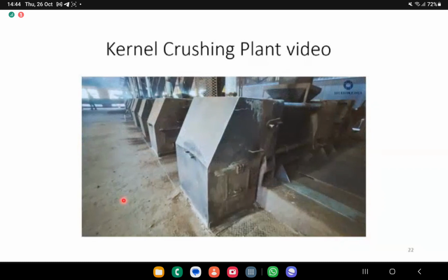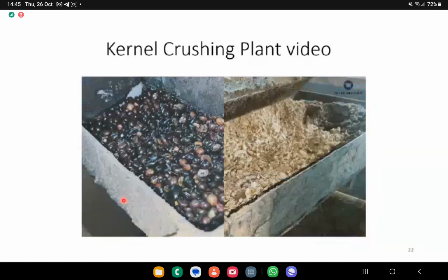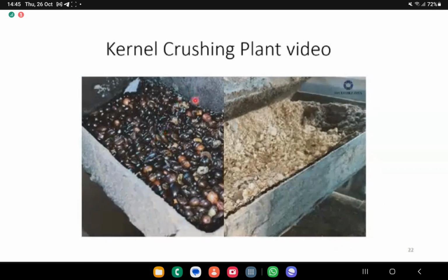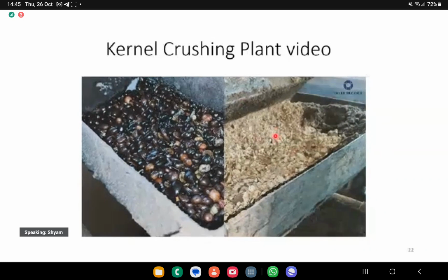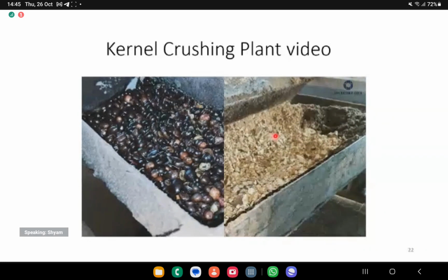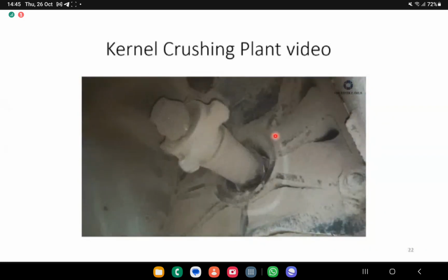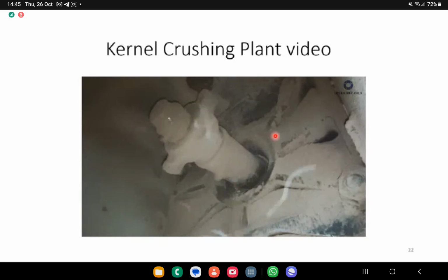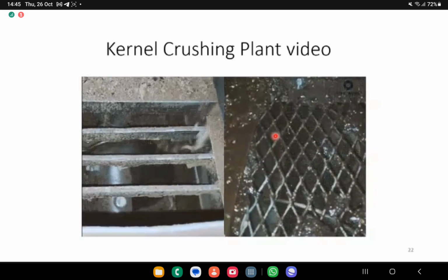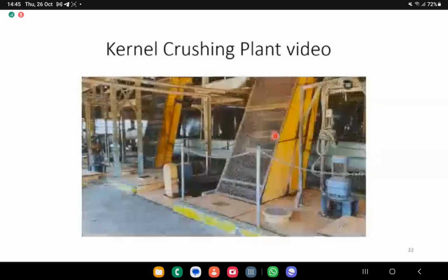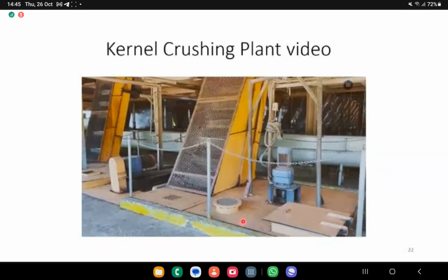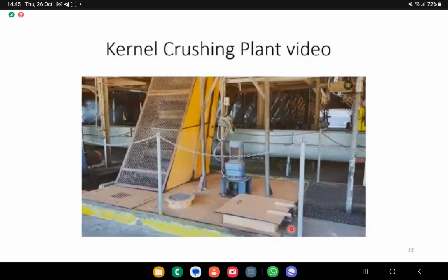Solid output of cake will be conveyed to, this is for the first pressing, this is second pressing, conveyor and bucket elevator to repeat the same CPKO extraction process in the second stage mechanical screw press. CPKO will be directed via screw conveyor to oil buffering. Unfiltered CPKO will be banked into underground tank and served as buffer for the next process.